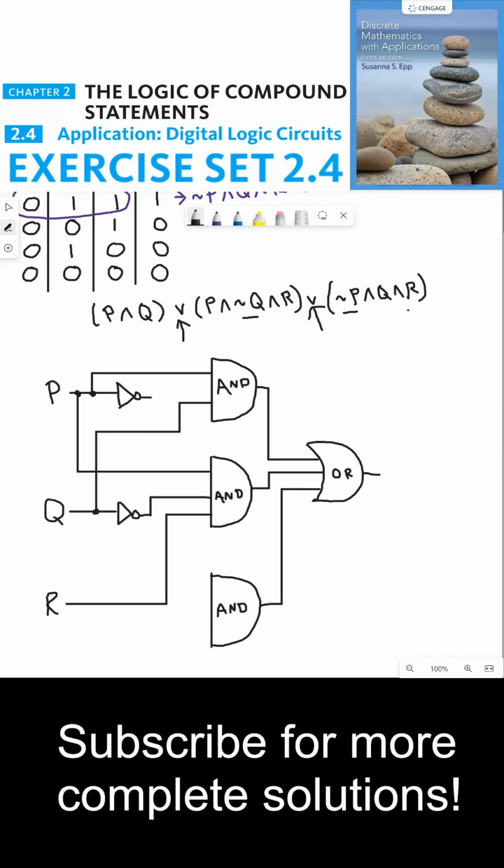And to build this last AND gate, I need not P and Q and R. So I already have not P built. I'm going to bring that down. Next, I need Q. I'm going to make another split from Q before the NOT gate, so I get a clean signal from Q. And then next, I need R, which means I need to create a split from my R input signal here and connect that with my AND gate. And that completes this circuit. My output here would be S.